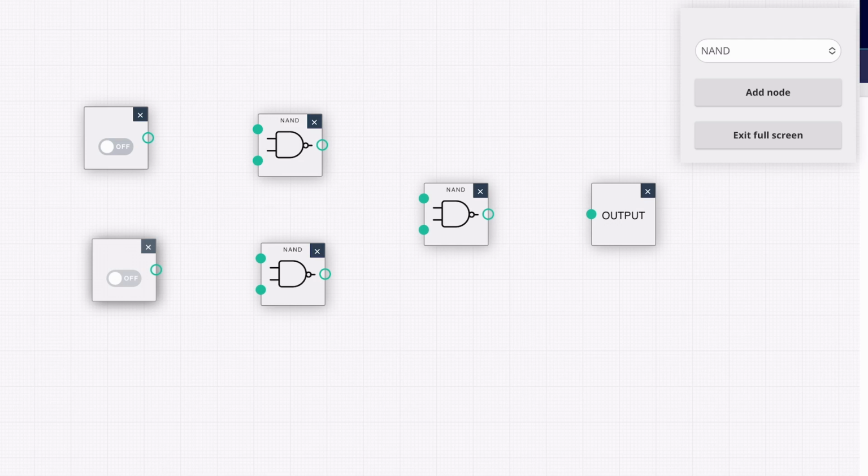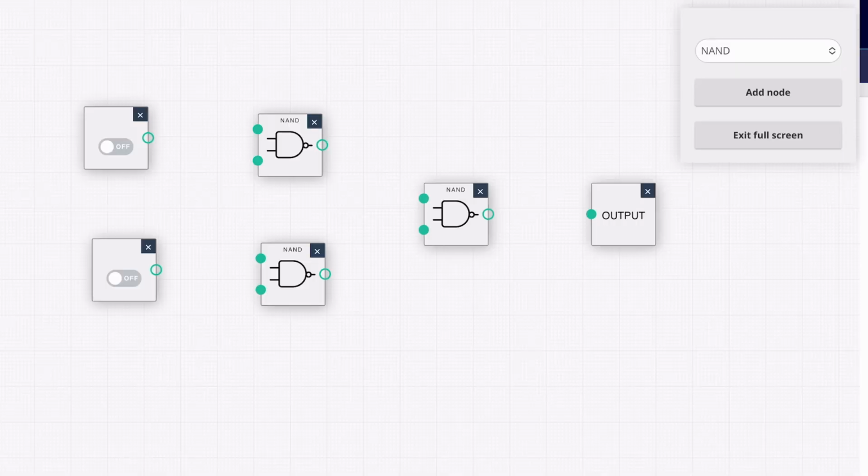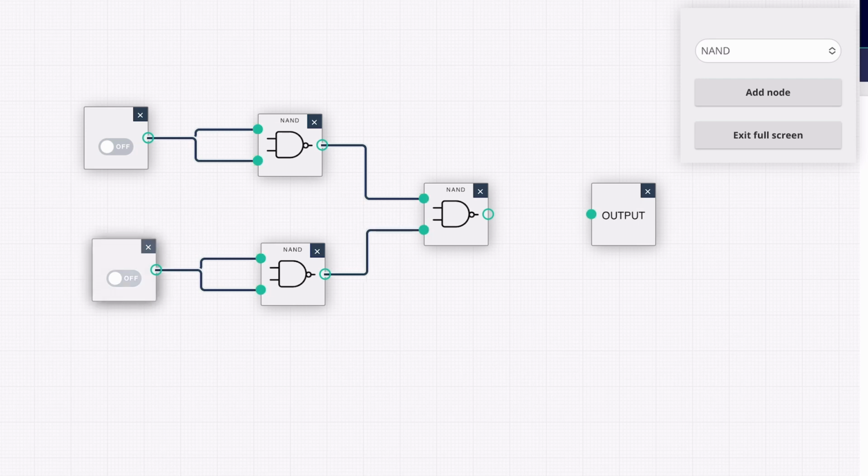The last gate that we want to replicate is the OR gate. The OR gate's output is 1 as long as at least one input is 1, and 0 if both inputs are 0. Coming back to using our NANDs, what we are doing is first inverting the inputs each by themselves. And if you remember from replicating the NOT gate, this is simply adding one input in both inputs of the NAND. And then we will connect the output of the NAND into this third NAND. So again, in the bottom input, we add both of these to the NAND's input, and then the output of this NAND to the third NAND. And the output of this third NAND will be our total system's output.